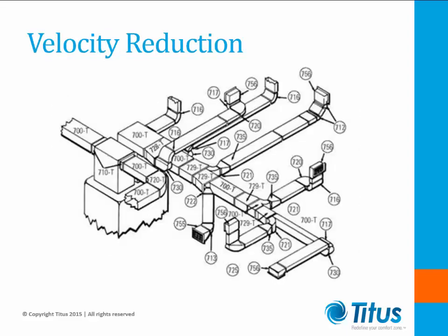Velocity reduction method. Velocity reduction is used in most small construction that is constructed without professional design services. It is an easily applied method. Examples of this would be residential replacement, small office installation, and interior renovations not requiring mechanical system design or permits. The sheer volume of this type of work has kept this rule of thumb method common.